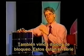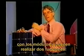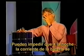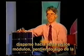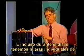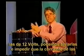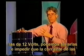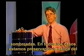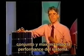We also looked at blocking diodes. These are in series with our modules and can perform 2 functions. They can prevent battery current from leaking backwards through our modules at night, thereby losing some precious energy that we made during the day. And even during the day, if we have individual strings higher than 12 volts, we can isolate those strings and prevent current from unshaded strings from flowing backward down a shaded string. In all cases, what we're doing is preserving array output and maximizing system performance.